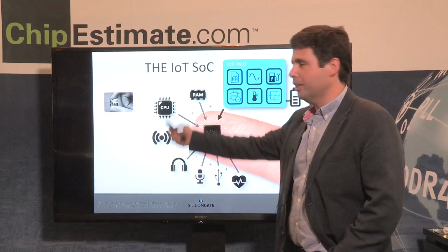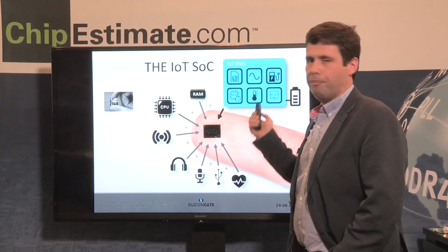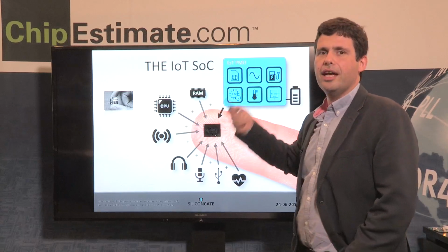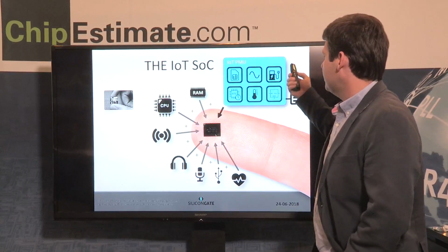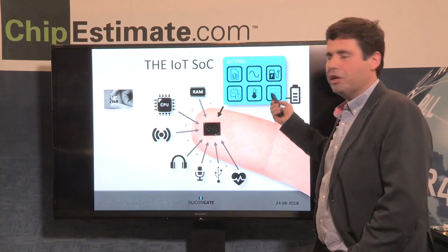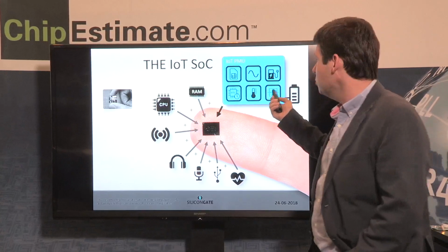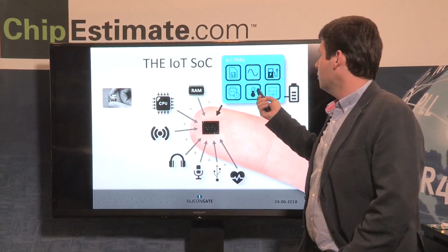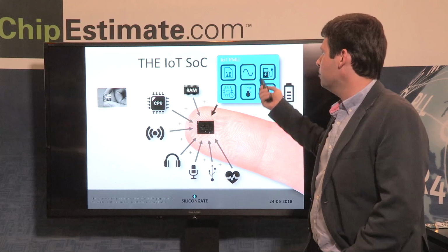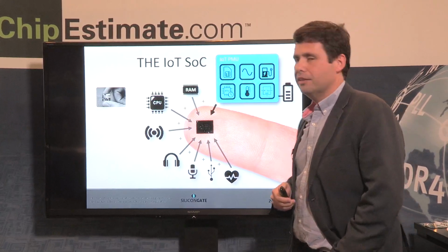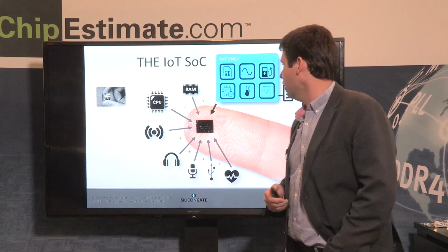And to supply all that, you need a lot of power management. This power management is usually a number of different IPs. It's the battery charger, all the regulators that you need, maybe 5 regulators, maybe 10, maybe 2, depends on the system. And you need the monitoring functions with measurements like temperature measurement, you need oscillators, you need real-time clock, and many times a SIM card interface.